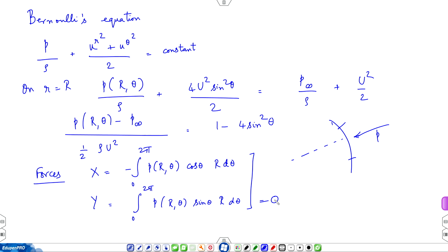So, when Re was very small, we did analysis for flow past a sphere, and we got C d is inversely proportional to Reynolds number, which matched experiments. Now, at the limit of Re becoming infinity, you get what looks like a flow field, but gives you 0 forces.